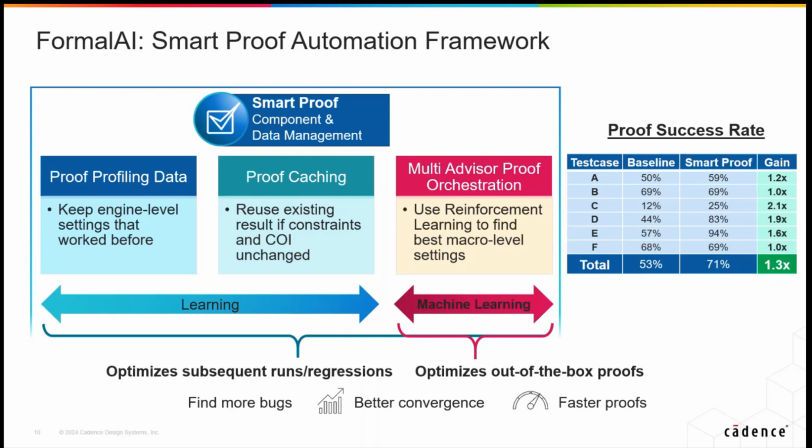Another thing it's looking at: let's say you're doing code check-ins and you have properties you've already verified. If you can validate that the cone of logic feeding those properties has not been impacted by the code change, there's no point in doing it again. So we can use the learning in the system to figure that out and be very fine-tuned on the formal side as well.